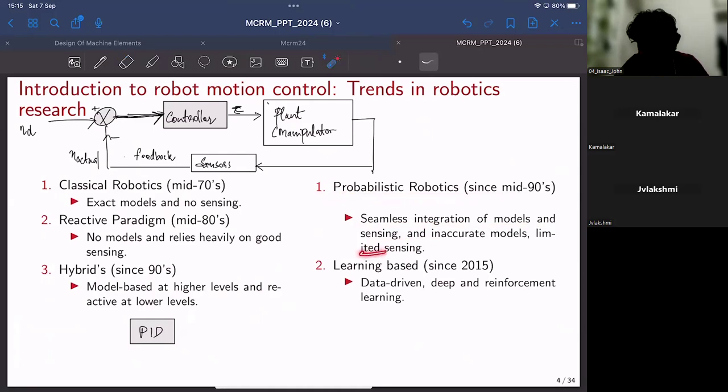And our sensors are also not 100% perfect, because there is a lot of noise associated with sensor measurements and readings. And if you're using multiple sensors for measuring the same thing, they can have some sort of interference amongst them. You can also call that sensor aliasing.